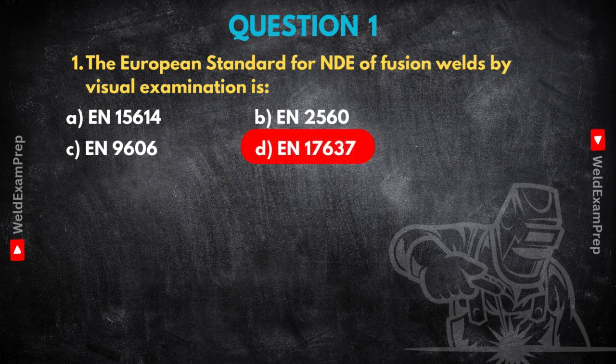Okay, D. This European standard, its title is pretty clear: Non-Destructive Testing of Welds, Visual testing of fusion-welded joints. It outlines everything: the specific methods, the conditions, the requirements for performing visual inspections. Things like optimal lighting conditions, even the qualifications needed for the personnel doing the inspection. It really is the blueprint for how to properly look at a weld and assess its surface integrity.